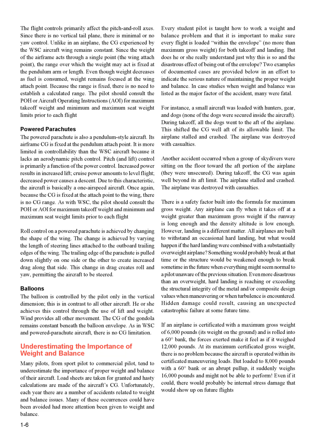Unlike in an airplane, the CG experienced by the WSC aircraft wing remains constant. Since the weight of the airframe acts through a single point, the wing attach point, the range over which the weight may act is fixed at the pendulum arm length. Even though weight decreases as fuel is consumed, weight remains focused at the wing attach point. Because the range is fixed, there is no need to establish a calculated range.